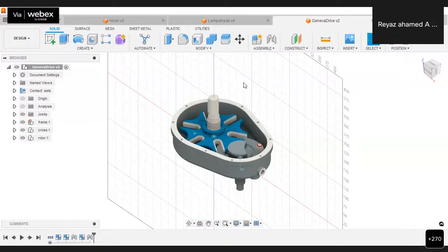That comes under what we already know. In assembly, there are two types: one is top-down assembly and the other is bottom-up assembly. Usually we go for bottom-up assembly only. In bottom-up assembly, we create several components, and then after getting into the assembly environment, we assemble each and every component in that particular assembly. We bring each component to that assembly, make them assemble, and then convert that into an assembly. That is bottom-up assembly.